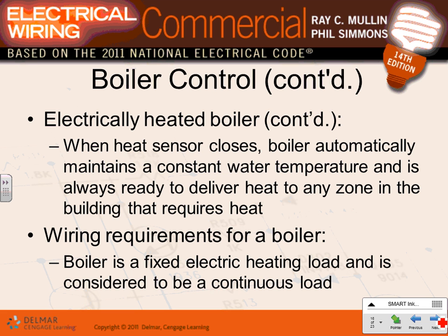There are zones, guys. These heaters have zones. I think we have a nice picture. And the way they do it, guys, they have a thermostat in every occupant area. The thermostat calls for heat. It will start the pump. The pump will pump hot water into that area. It goes through a system, a blower, and blows air through it, and you got yourself what? You got yourself hot air.